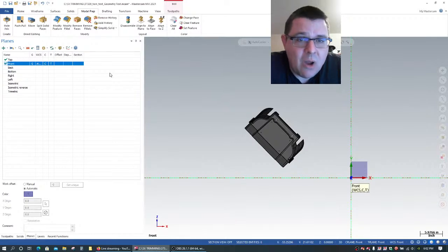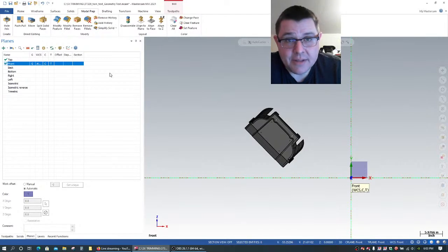Which is the right way to do it? The right way to do it is the way that works for you. It's the way that works with your machine and your shop and your shop's requirements, right? Because like I said, I've seen 10 different ways to do everything. At Boeing with our machines, we did not use a work offset. We didn't use G54, G55, G56. The way they had set up the machine was to use what they call a local work offset, G92, because we had such long beds, 420-inch long beds in X.